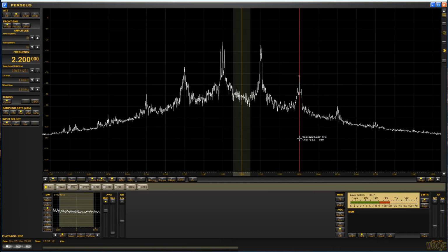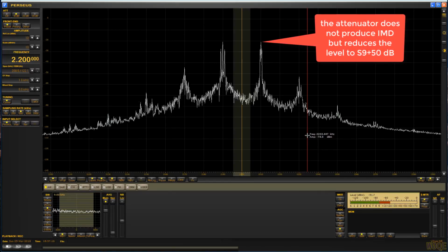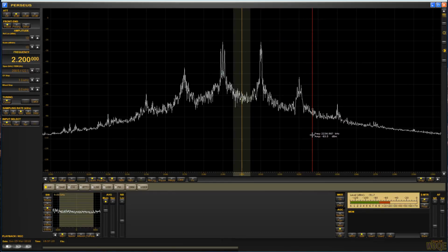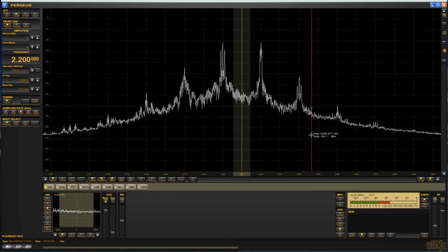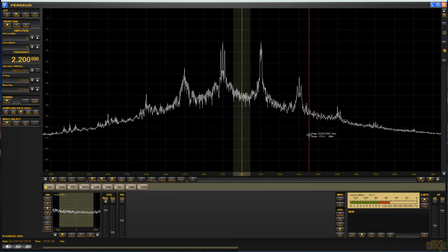These two generators are both hooked directly in parallel, and then there's an attenuator on the output to produce the IMD. But this is what you get with IMD, and it occurs anytime you have strong signals nearby that cause some nonlinearities in a circuit, particularly your receiver, and then other products mix with those, and the next thing you know is you hear stuff where it really doesn't belong.